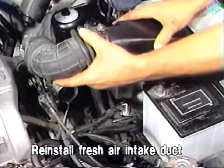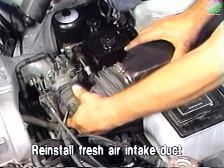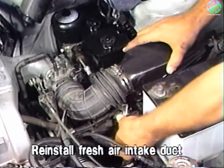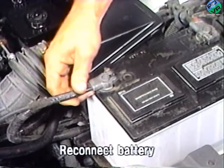Next, on all models, reinstall the fresh air intake duct and the air cleaner assembly on AS body vehicles. Now, reconnect the negative battery terminal.